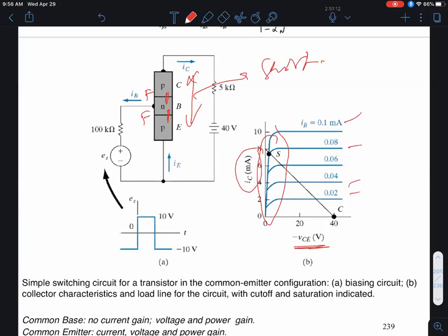Now it kind of looks like the MOSFET output characteristics, but of course it's a different device altogether, right? In the MOSFET, it was ID versus VD for different gate voltages, but here now I'm looking at the collector current as a function of collector emitter voltage for different base currents, okay? Now if I was to forward bias both junctions, what is my VCE magnitude going to be?